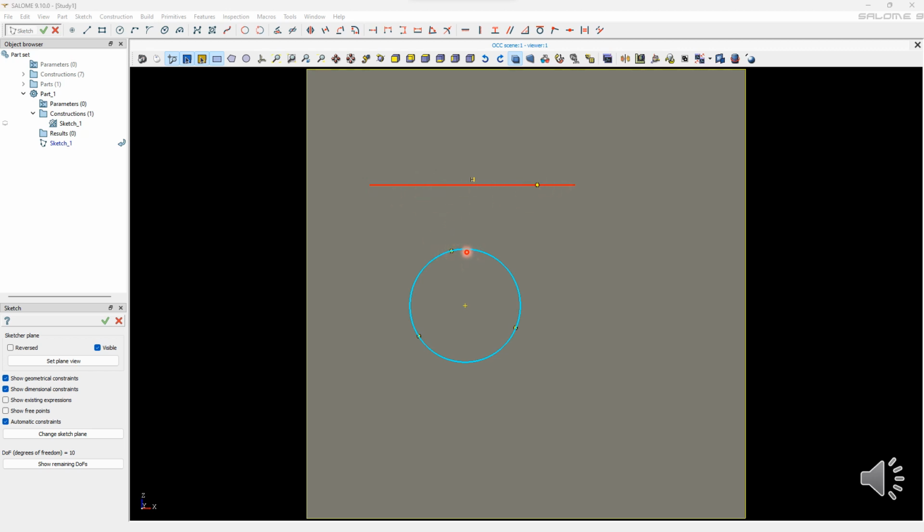Here we have 2 points, but I'm not able to select the segments. Now I'll select the split operation, and here you can see I can. This is the point, and you can see that this edge is split into 2. This was not possible before, but after the operation it is possible to split the segments.